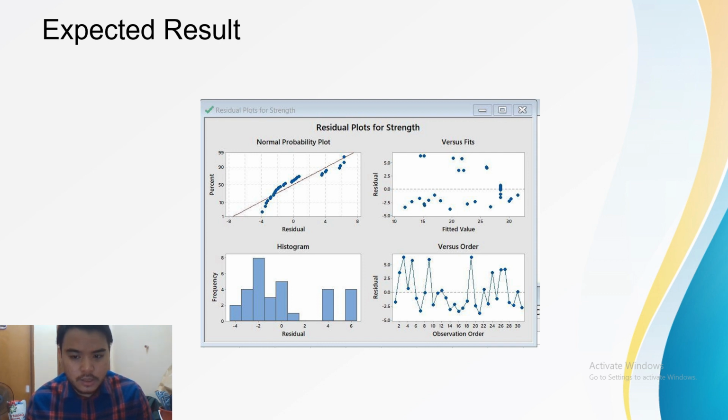We can see the relative magnitude of the various effects and visually identify the significant effects using the Pareto plot of the effects. Furthermore, we can observe that hot bar T multiplied by dwell time has the biggest influence because it stretches the furthest. The points on the normal probability plot do not follow a straight line in the residual plot. This may be resolved by reducing the model.